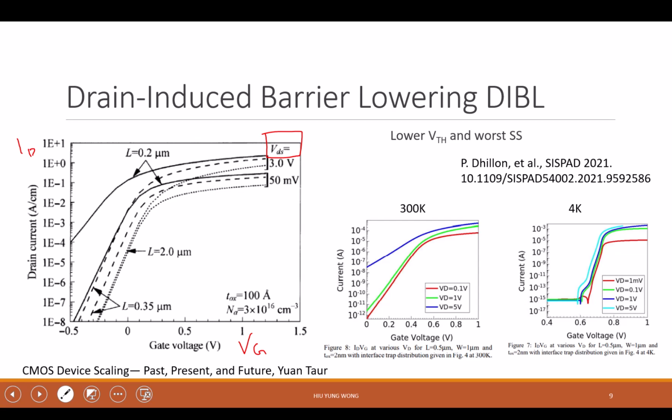I mean, how should I say that? You see that they have pretty strict lines, right? So it really doesn't matter which one you pick as long as it is within this region. Because this is not the one that you use to do the leakage calculation, right? Leakage depends on zero bias. And all you want is just the relative shift, because if you shift by that much for 1e minus 6, you approximately also shift by that much for 1e minus 4. But I really don't know. In the past, usually we just pick 1 nanoamp per micron. No, 1e minus 6, but that is for advanced devices. These are all old papers, so sorry, everyone. But I feel that it doesn't matter. Makes sense? For the constant current method.